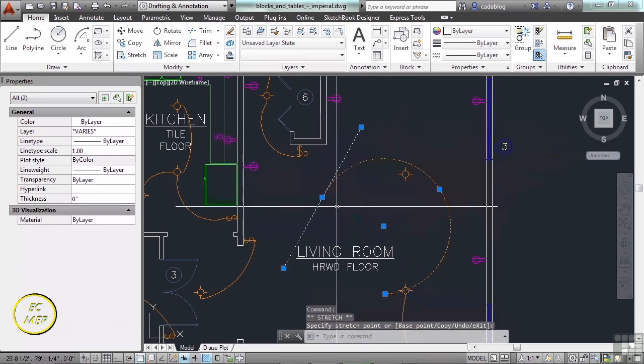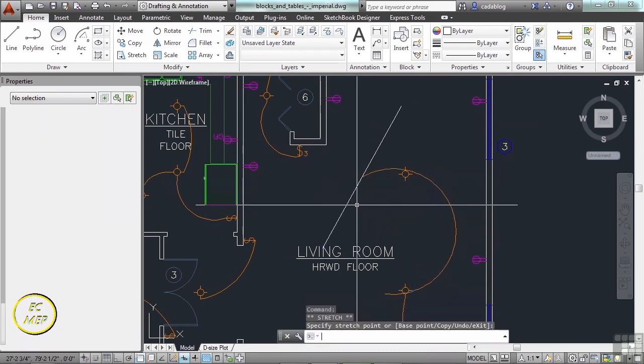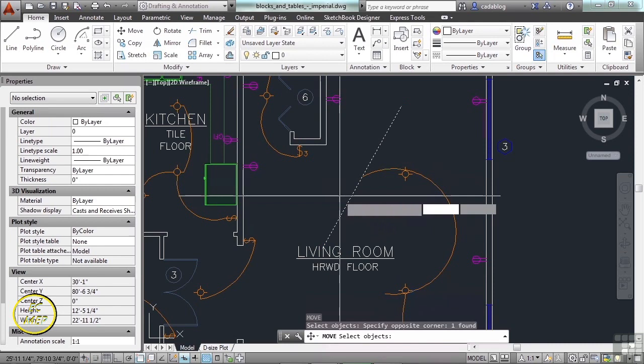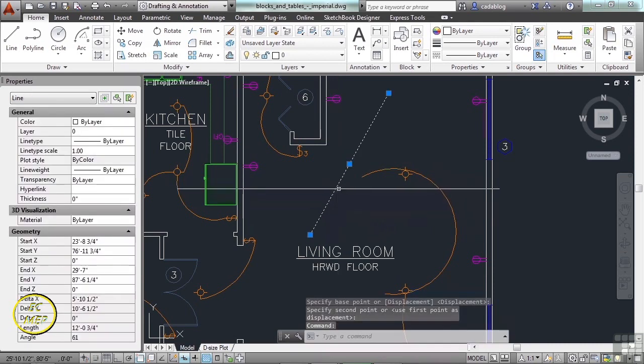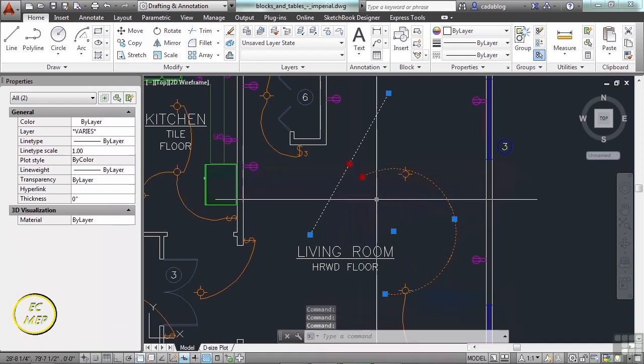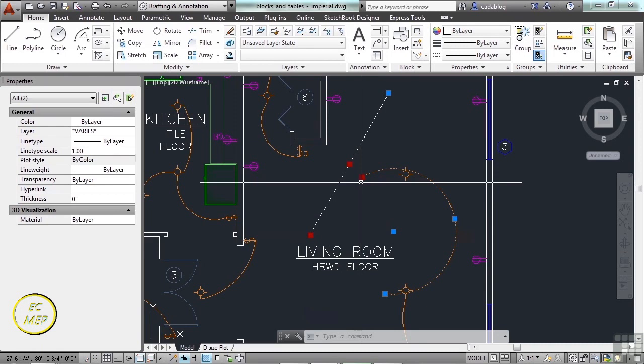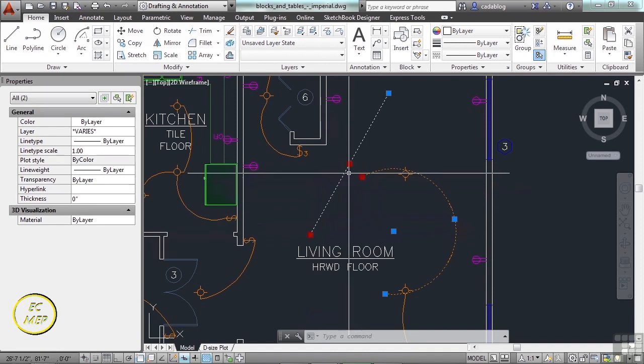But what you can do is hot grip something. So if I select the line and the arc, and I hold down the Shift key, and I pick multiple grips, the relationship between those hot grips, that's what these are called, hot grips, they turn red, like red hot. This relationship of these 3 points, the way they relate to geometrically, will not change.